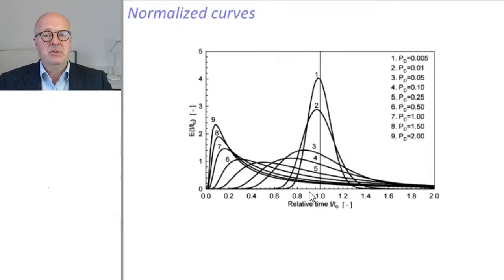We have divided by velocity and scale. So we can now compare different trace experiments that have been carried out in systems of different velocity or different scale. Now, this can actually be funny and very revealing, very interesting. We can compare a trace experiment in a huge aquifer that is 10 kilometers long with a column experiment of 0.5 meter.